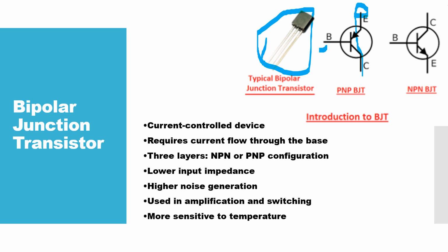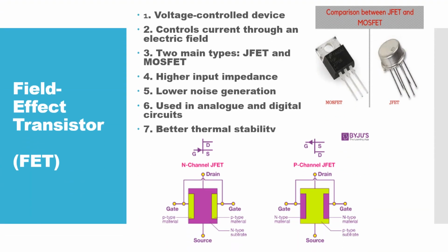Like I said, in any electronic switching you'll be adopting in anything, please always consider the load. The load can contribute to the temperature, and most of these electronic switching devices are sensitive to temperature. Now we quickly move to the field effect transistor.